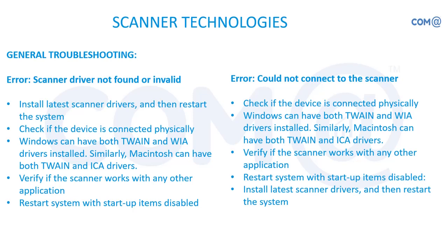So, could not connect to the scanner. You are physically connected through the USB port and using the USB cable, but not actually connected. In the sense that the software is not recognizing the connection between the scanner and the computer. The physical wire connects both the USB port and the scanner, but it is not getting recognized. Maybe the cable has a loose connection, or the USB port has an option for the latest speed or old speed. Sometimes the scanner works only with the latest speed, so that it captures more data from the system. Those are all the things you have to check.